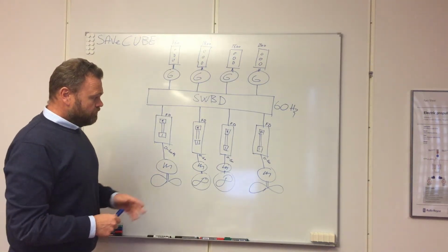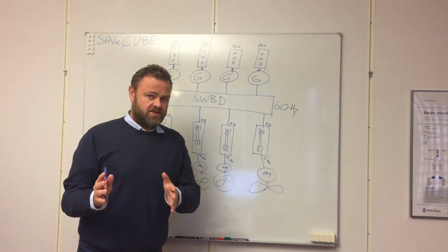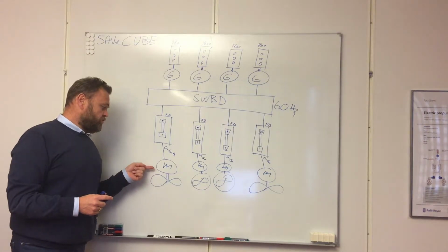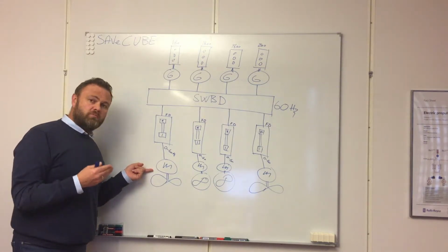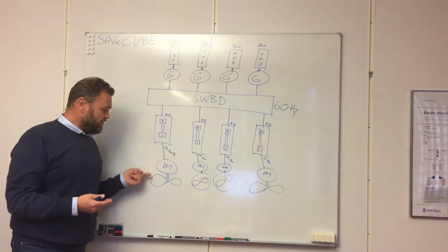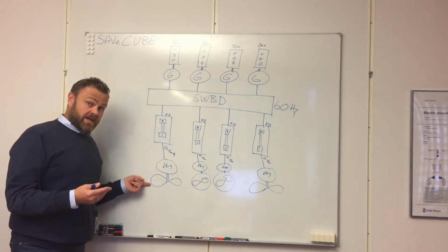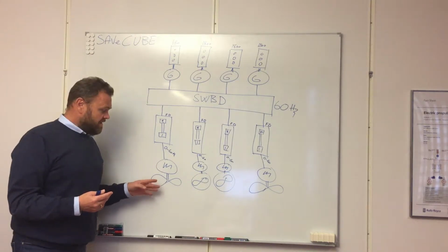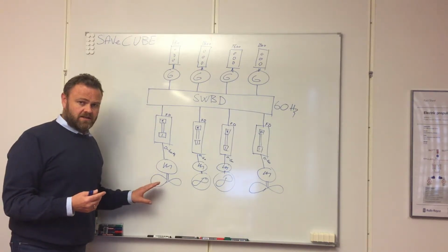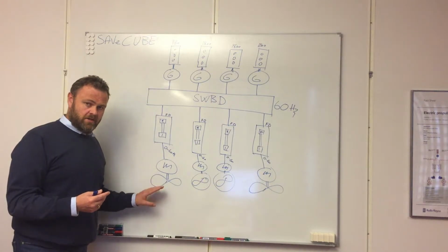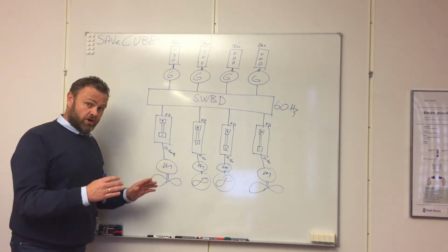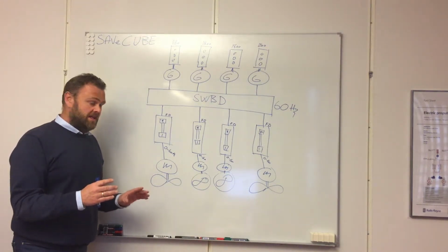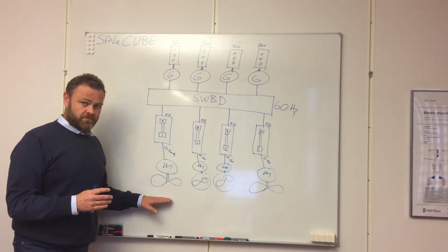Okay, we have in another session discussed why we would like to adjust the RPM freely on the propellers. That is due to the propeller losses. There is a huge saving in regulating the RPM down to a lower RPM when you need lower thrust.